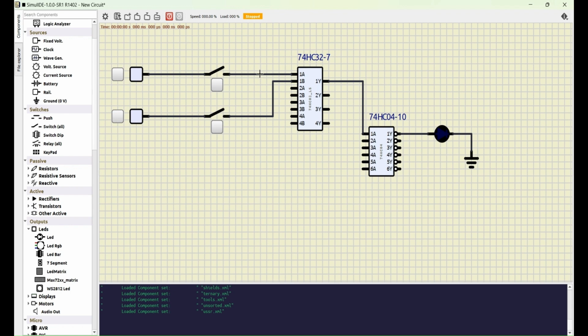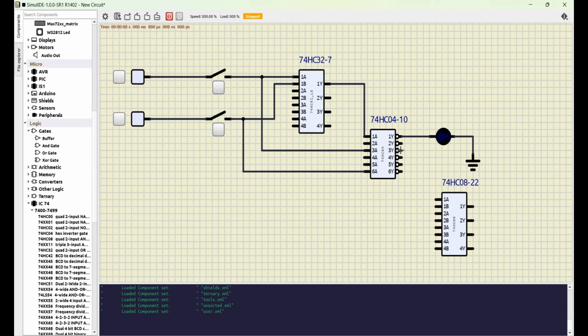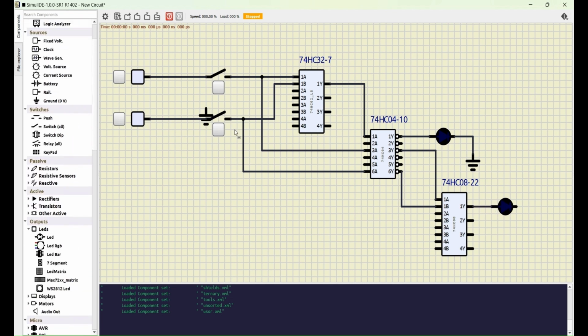In order to draw the circuit for the right hand side, we invert the inputs using the 7404 IC. Then we take the IC 7408. The inverted inputs are fed into the input pins of AND gate. Here the inputs are fed into the input pins 1A and 1B. The corresponding outputs from 1Y will be connected to a LED. Then the LED will be connected to the ground.